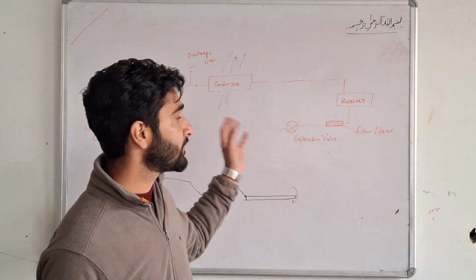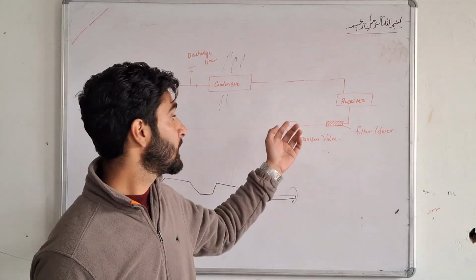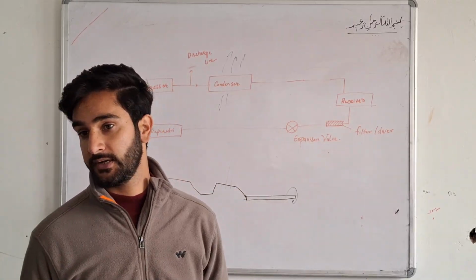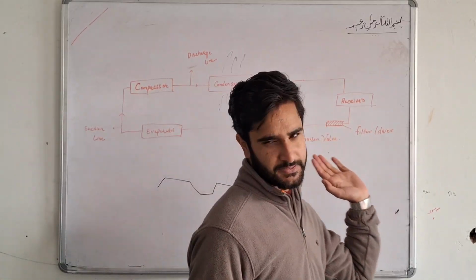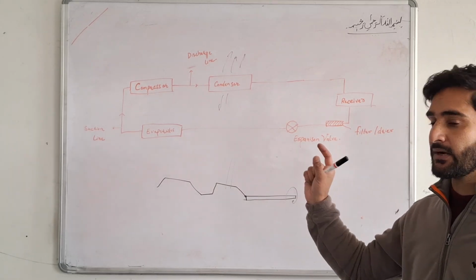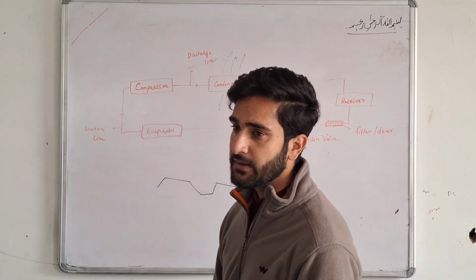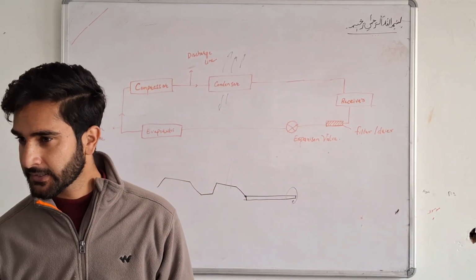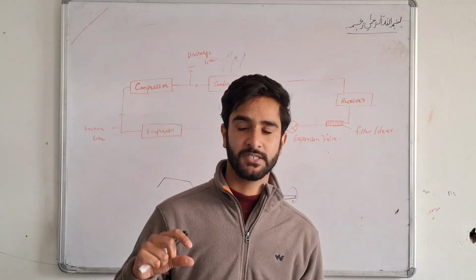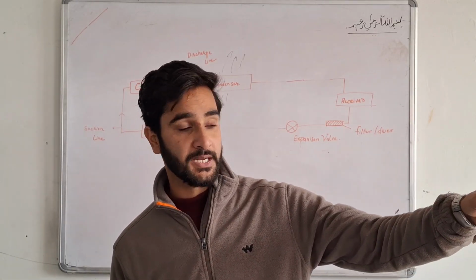ओके, समटाइम्स यहाँ पे बहुत सारी गर्म चीजें रखी हैं तो बहुत सारी हीट ले जानी पड़ेगी, तो सप्लाई ऑफ रेफ्रिजरेंट मस्ट बी ग्रेटर, सो इट सप्लाइज द हायर अमाउंट ऑफ रेफ्रिजरेंट. It is like a tank, a refrigerant tank. It stores the refrigerant and it supplies according to the requirement. ठीक है. The expansion valve can be of the electromagnetic type, it may be sensory type, it may be screw type. Here we have the expansion valve, a simple thermostatic expansion valve.